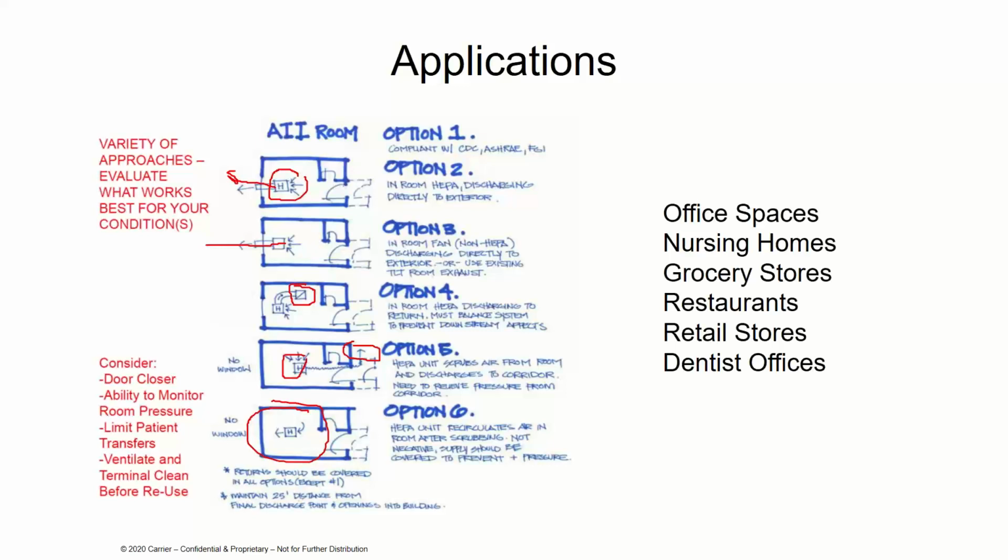We still have the problem that viruses are tiny, and they don't like to get stuck in the airflow path. So we'll get some of them this way, but there's still going to be some in the room that never get into the airstream. But this helps out quite a bit. If I can get a certain percentage of them, it's better than doing nothing. Usually we try to combine this. Let's say we're doing that classroom where they don't have good ventilation. We try to combine this room by room HEPA solution in combination with one of the air purification technologies to kind of double dip our efforts on that.